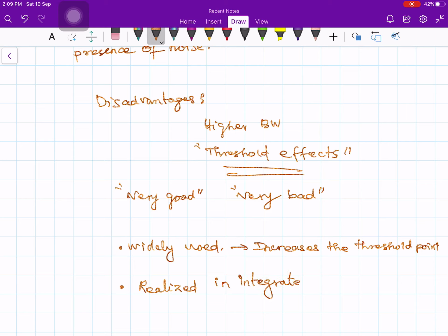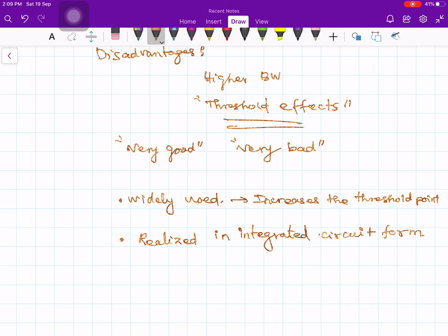If you recall from your frequency discriminator, we used transformers, inductors, capacitors, and so on and so forth, in your balanced discriminator. That is based on tuned circuits, stagger tuned circuits. It has two slope circuits that we have talked about. They will typically be realized by using the linear portion of the resonant circuit, which has a parallel LC circuit. Whereas there will be no inductors and capacitors in this realization. So that is the advantage of these feedback